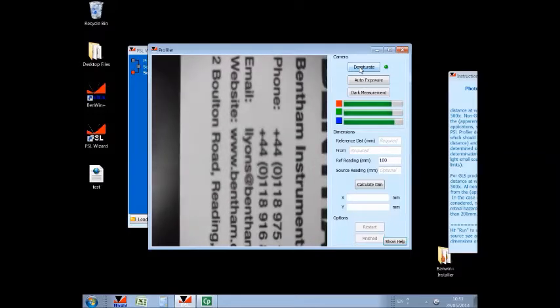We can do so by rotating the rear thumbscrew. Rotating clockwise results in the imaging of a plane further from the PSL Profiler, and vice versa. So I will adjust the position to get the alignment aid into focus, which we have here done.